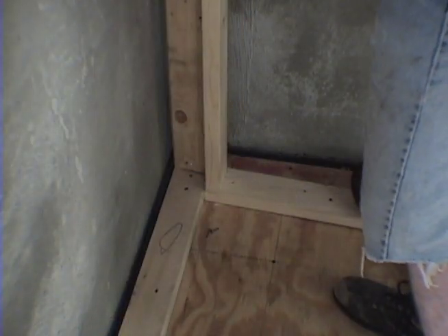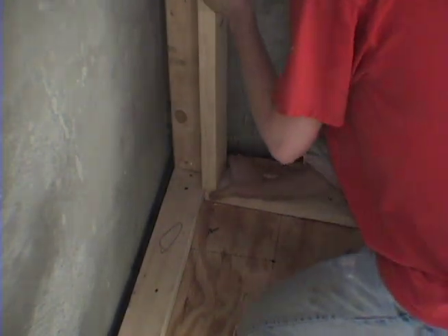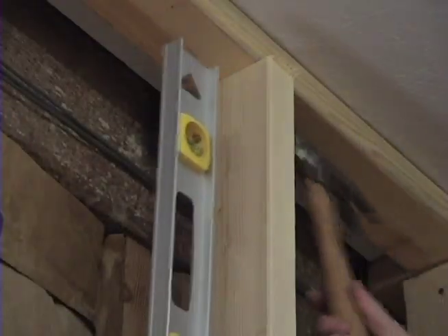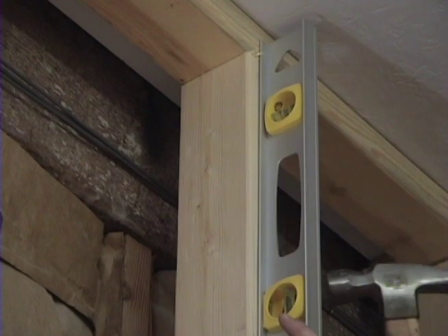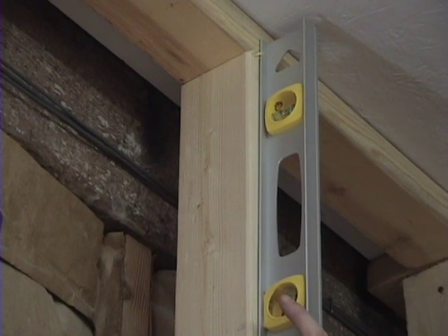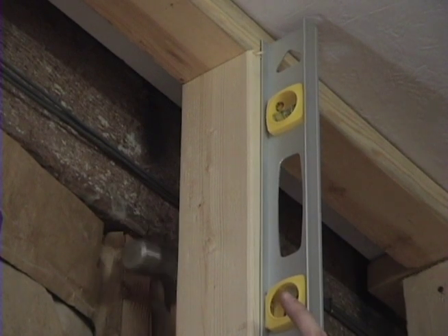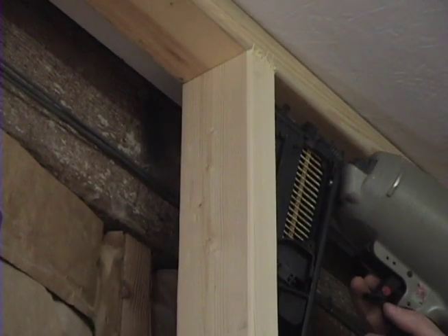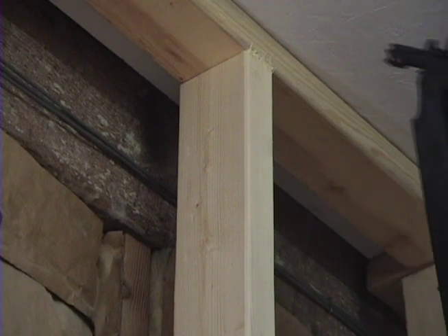You can use at least 3 nails to hold the stud in place, 1 on one side and 2 on the other side. Line up the bottom first and shoot a nail into it to hold it in place. Then use your level to make sure they are straight from side to side and back to front. Never assume that if it looks straight or lines up that it is straight. Use your hammer to gently tap each stud into place. Place another nail in at the top and double check your framing. If it's good, then put in the other nails.